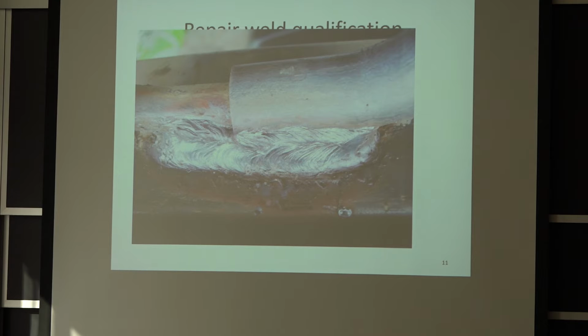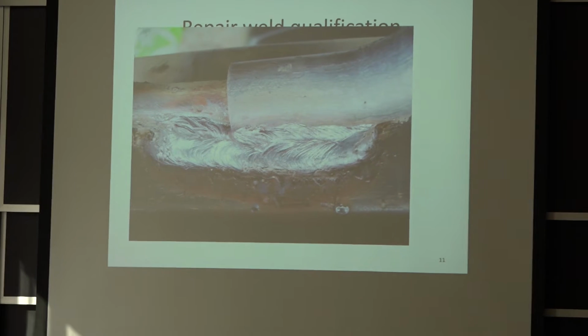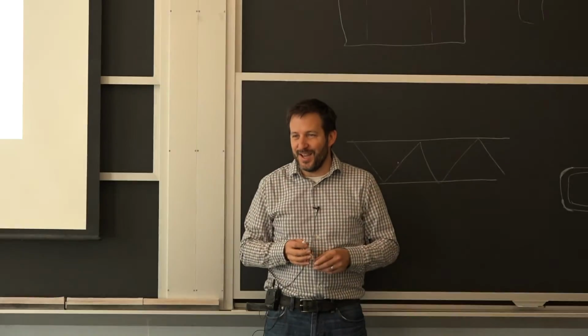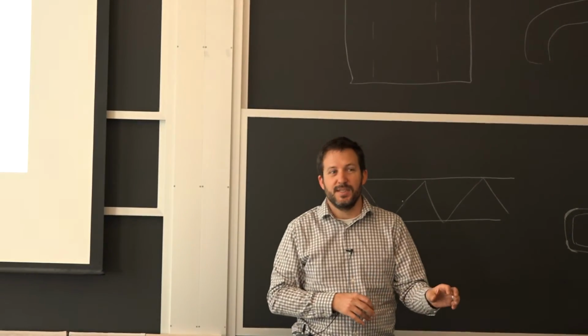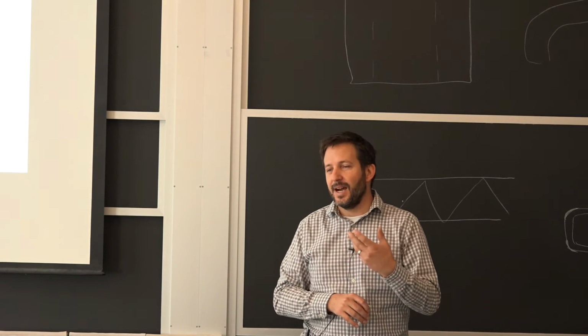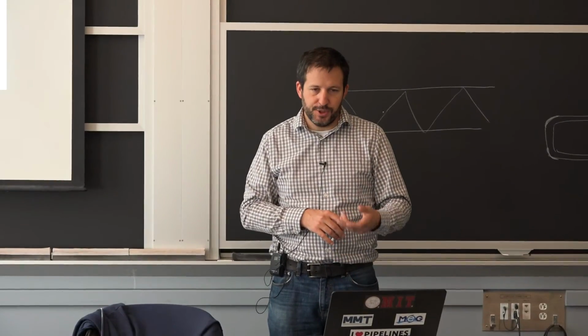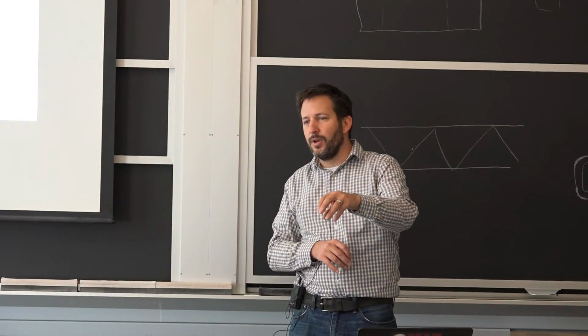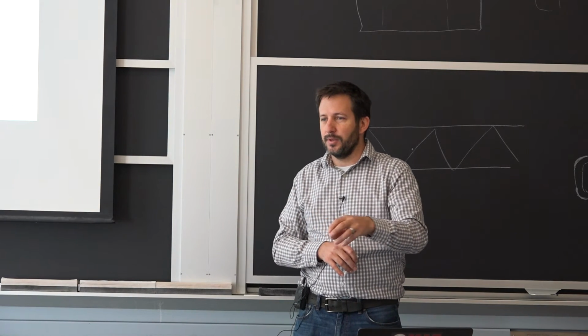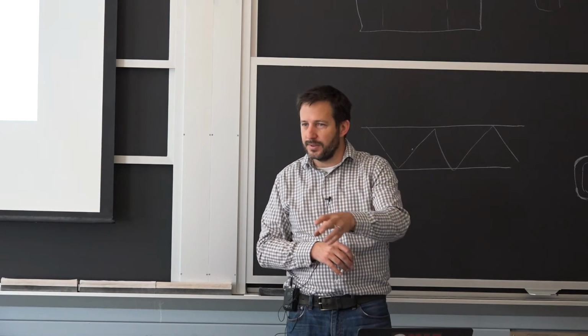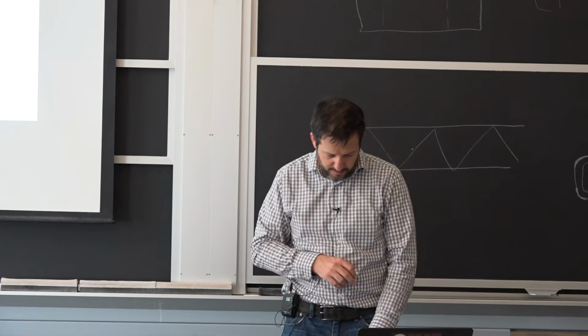Now, this weld, a reason I photographed it, was one of the best that I've seen for this component because it had the fusion on both sides, and the roughness is really not a problem. So if you see a weld on sport equipment that is very, very smooth, that itself is not a sign of quality. You really want to see how much it was fused, whether there's porosity in it, and things like that. But the striations are just the process of that pool growing step by step, just like when rocks solidify around volcanoes. It gives these cycles. It's very much the same.